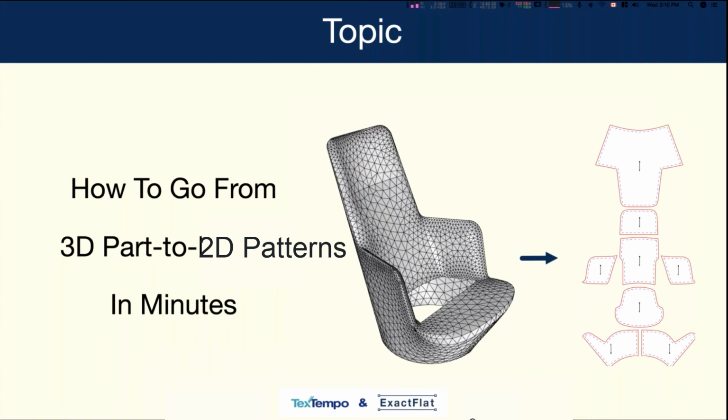Materials like leather don't really stretch all that much, so you may need to create additional pattern pieces. But if you're working with a woven material, or if you're even knitting your shoes using a 3D knitting process, then that might be fine for your process. So it really depends on your manufacturing techniques. If you're only splitting it in half, obviously there's going to be quite a bit of double curvature there. So ExactFlat will expand it as best as it can, but for those types of shapes with only one split line down the center, usually there is quite a bit of strain in the pattern piece.